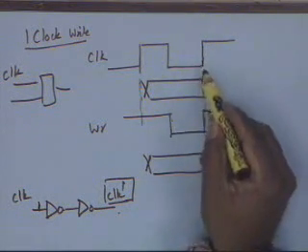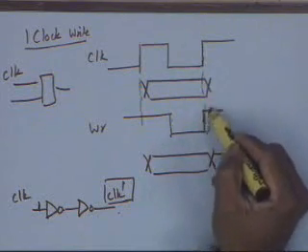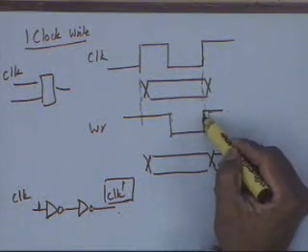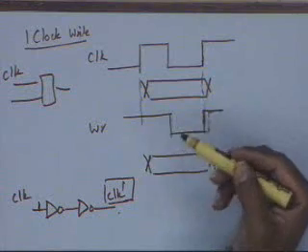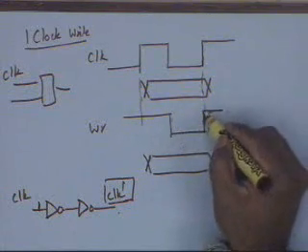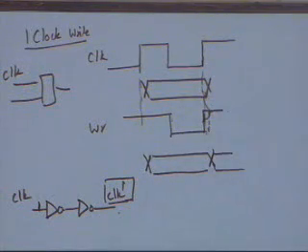Because this clock is delayed, this edge relationship will be maintained. Of course, the hold time required is fairly small, only a couple of nanoseconds. So you will be able to meet the requirement that this changes afterwards. So when you are doing a memory design, you have to bother about this.